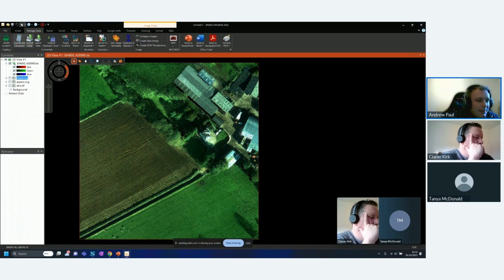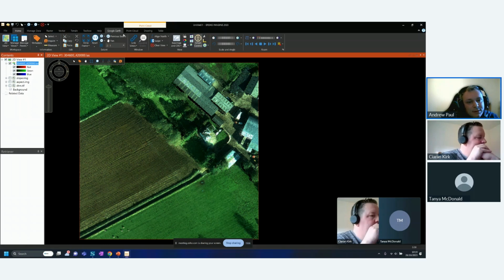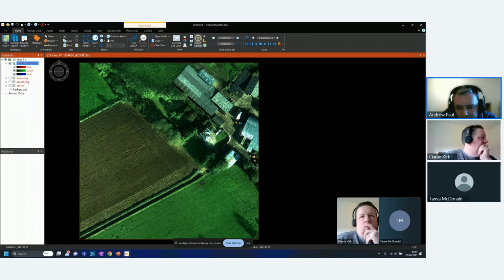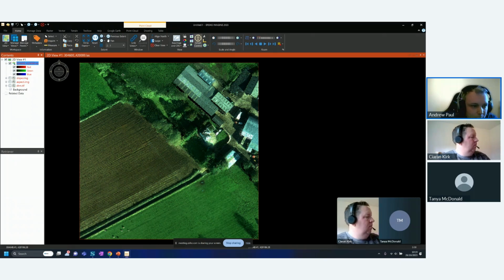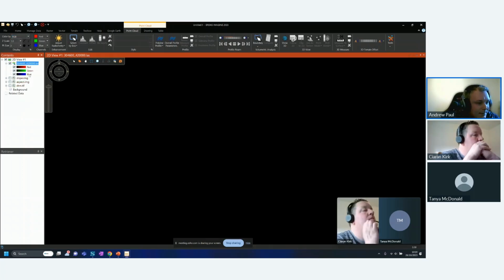And then when we come into some of the data sets, when you click on the data set, you will see some new tools have just opened up because we're looking at a point cloud data set here. This little sample of data is available on Open Data Northern Ireland. It was captured by the Department of Infrastructure as part of the A26 upgrade work. So you can see we've got our point cloud here, and it's been colored. And you can see we've got our RGB highlighted on the point cloud data. So we can see everything's displaying as we expect.